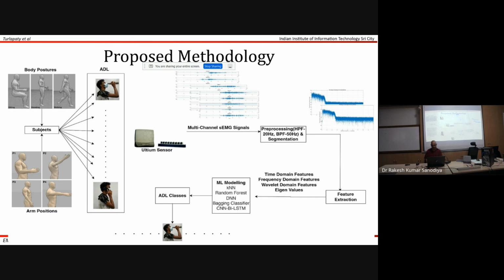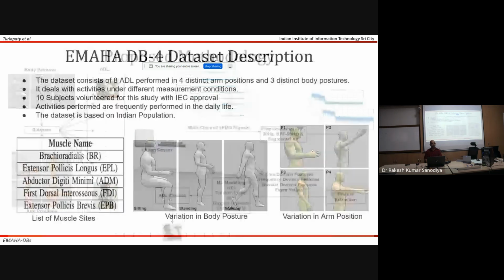Once we have the signals and do some basic pre-processing, for example, we apply a high-pass filter, that means about 20 Hz, everything below is filtered out. Then we remove any line noise, and then we can extract multiple features, which we will describe later. These features are fed to some of the existing classifiers, and also another recent hybrid deep learning architecture. Obviously, the goal is to determine the corresponding class.